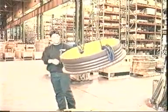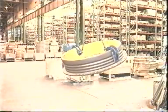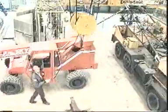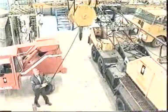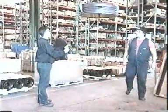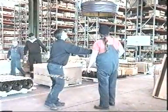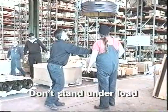Never leave a load unattended, even for a short period. Ensure that the hook or load is sufficiently raised to avoid collision with any object during horizontal movement. When a load has been suspended, it is vital that no one stands under the load. Anything could happen, so don't take the risk.